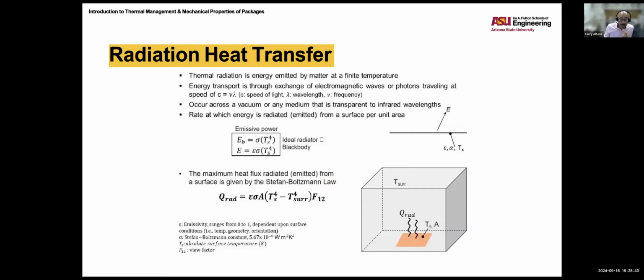So now we need to come up with our convection resistance, the resistance of the spreader, the resistance of the TIM, and the die. If we utilize our previous slide that gave us the values, convection is going to be 1 over the heat transfer coefficient times the area of the spreader.